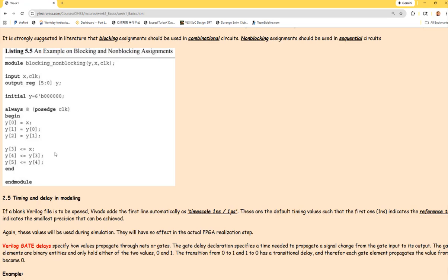Another reason is for the microcontrollers, they want to keep it more general purpose. So for our microcontrollers, we have a lot of ADCs, a lot of other things. And like ADCs, they probably will cap the speed at a certain level. But FPGAs don't really have a lot of analog stuff in there, so they don't have to accommodate all the low speed blocks inside the FPGA. So most of the time, FPGAs are just a pure digital device. Okay?